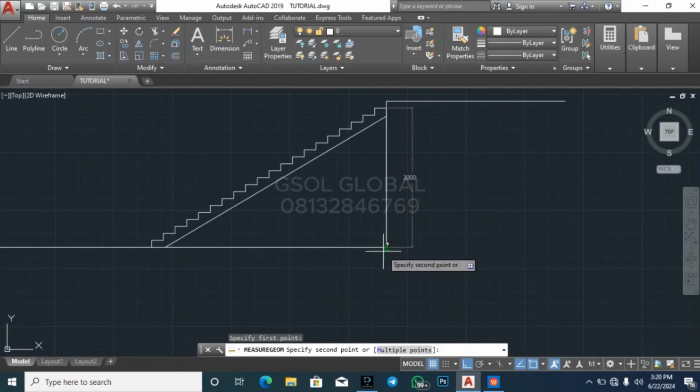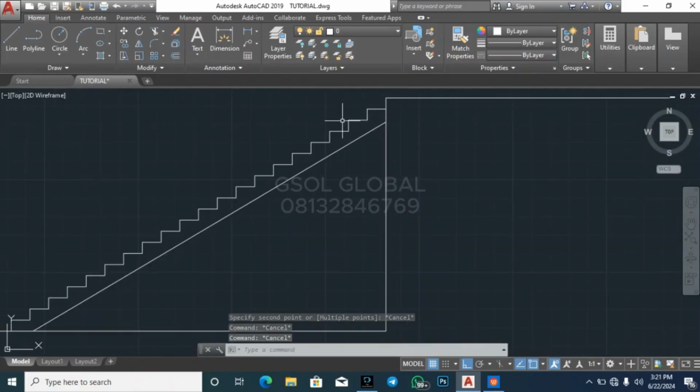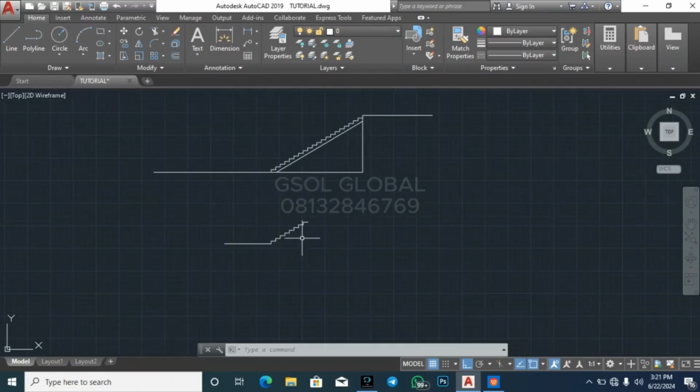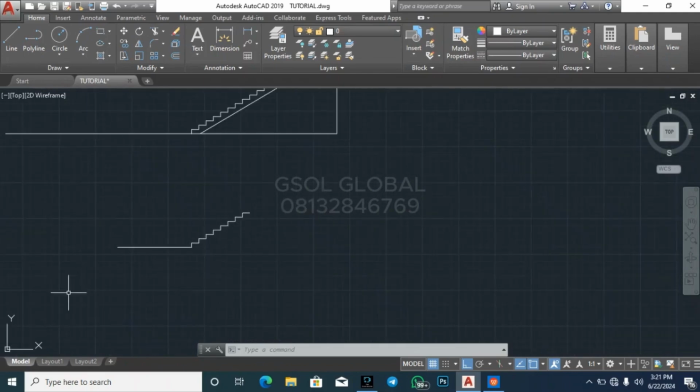So you see it, right? This particular 3 meters you are seeing here is made up of all risers. Now, to attain that height of 3 meters, note that there will be 20 risers here to get to that height of 3 meters.